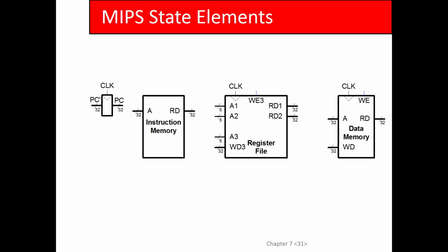Usually, it doesn't have to be. We've done some FPGA designs that don't follow those rules, but in general, that's the presumption on a typical computer. But for some reason, these textbooks always show these as 2 separate memories. They just represent 2 ports. In reality, on a CPU, you're going to have an instruction and a data cache, so you do have 2 physical memories on a real processor, but those are just caches of a much larger unified memory. Does that answer your question? Yeah, it's a little confusing.